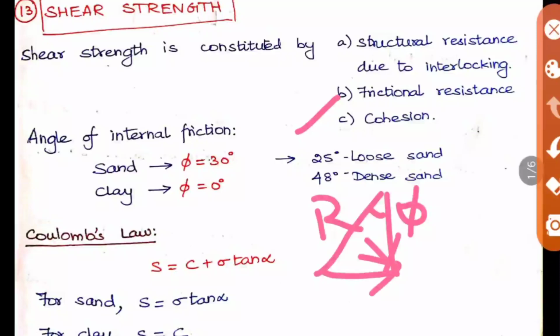And angle of repose is also another important one. That is nothing but when you pour soil on any flat place, you will get the soil like this. So this angle is what they call the angle of repose. These two are very important for the soil to be studied.